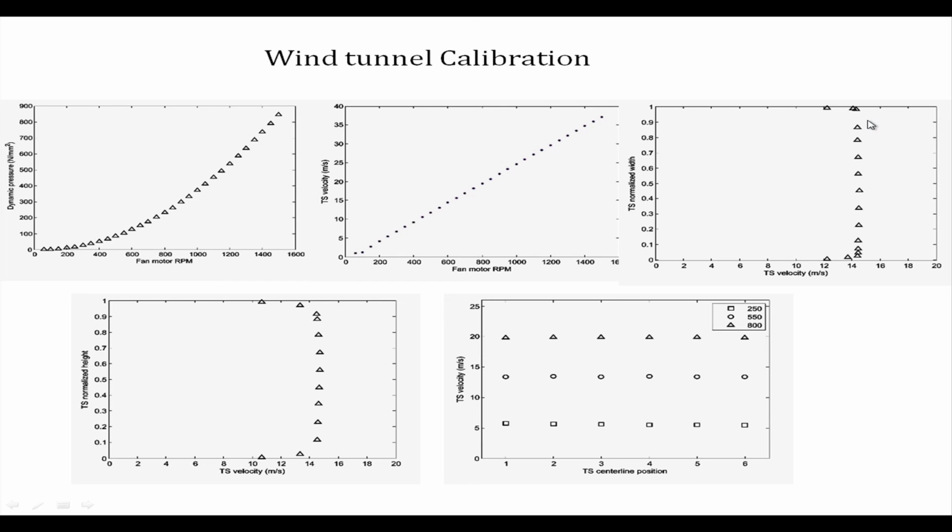So, we said that we need a good amount of the cross section to be having a uniform flow field, and we see that over a fairly large distance it is more or less uniform. Now, keep one thing in mind, that this is an average data. Okay, you have acquired data for some time and then averaged it. So, it does not mean that all the time when you acquired it, it actually stood at that value specifically. No, it might have fluctuated here and there, slightly here and there, but when you did a time mean of it, you got a reasonably good distribution.